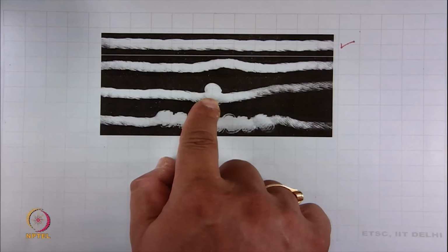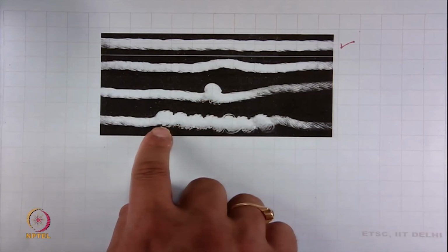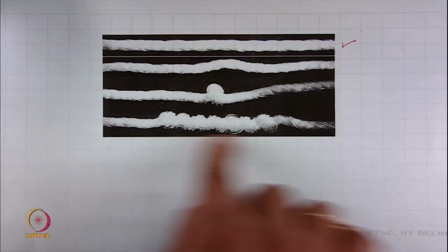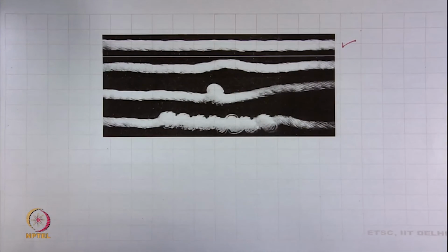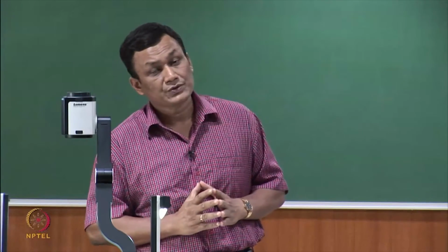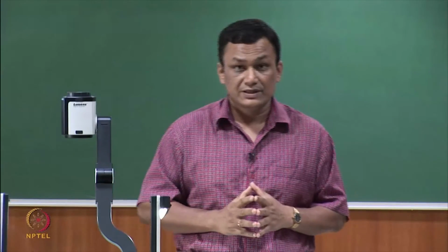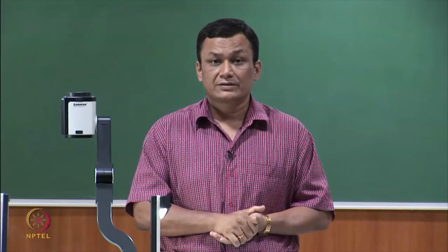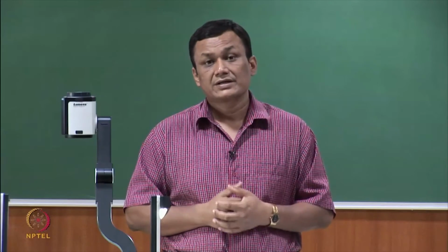If you still go on increasing twist, then you will see total disruption, destruction of the yarn structure. So, it is also possible to determine the limit of twisting experimentally, and by using the helical model we have also learnt how to explain it scientifically.